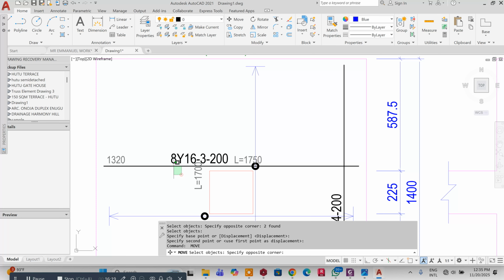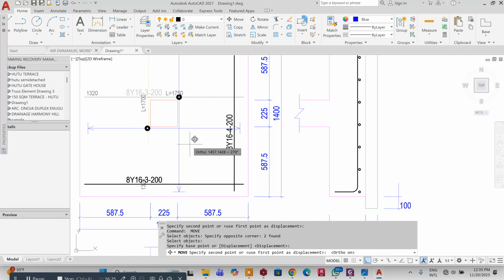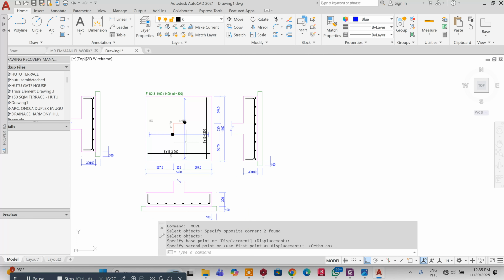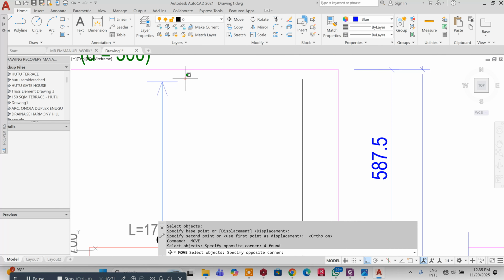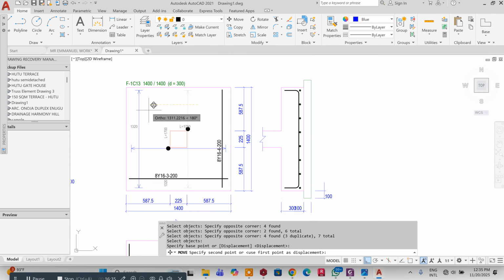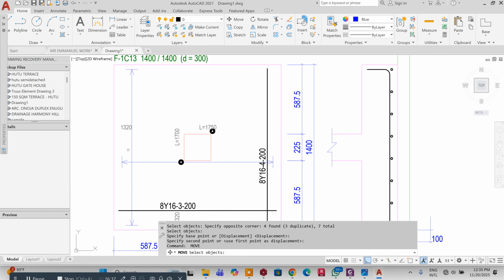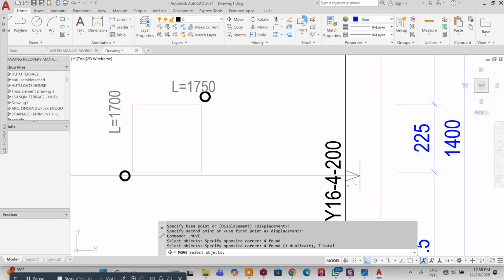So my advice is always that when you are trying to carry out design from your ProtaStructure, always try to make your footings uniform. It's not always good that you have so many sizes of footings. Let's say I have 1.4, then I will be having 1.5, I will be having 1.550.